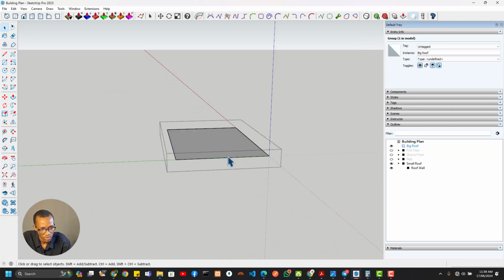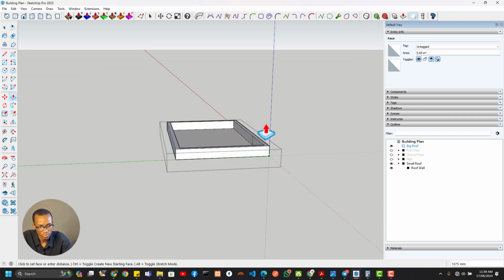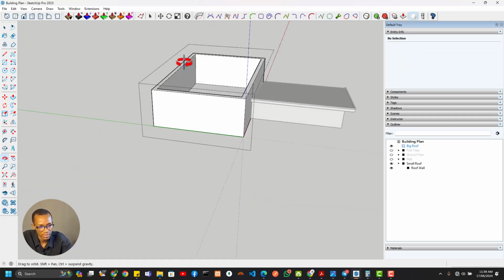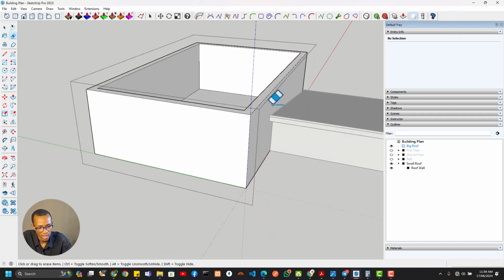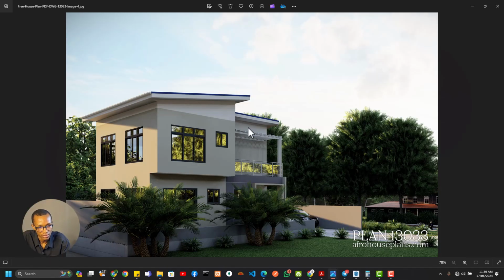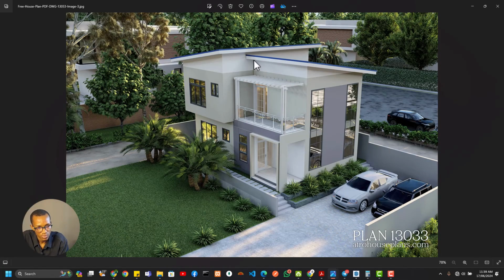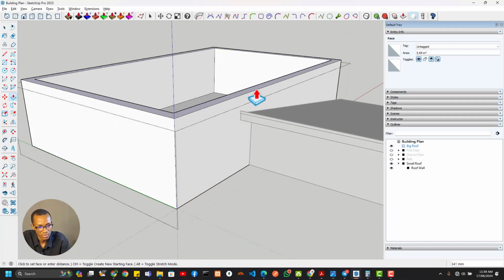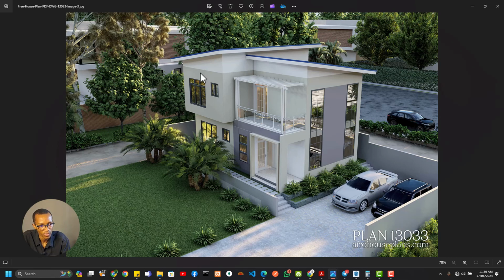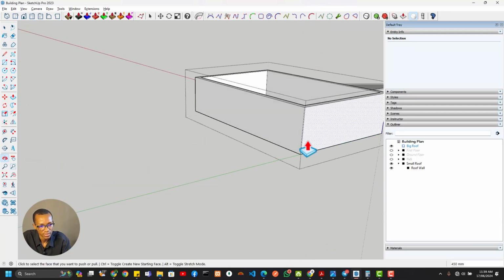All right. So this one goes up this way. So I measure 230 for the walls and I pull it up. All right. So I'm pushing it up. So let me unhide the other side because I want to know how high it goes. I want it to be almost as high, but let me see the difference in height. All right. So you can see this is where that wall ends. So like maybe 450 extra. So let's see, take this up by 450 extra. All right. So then it falls down to the end. Right, so this part goes up by 300 just as the other side.